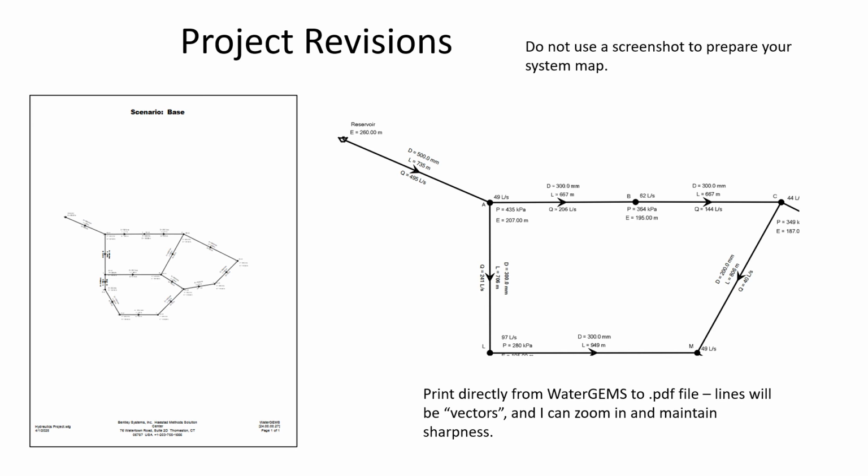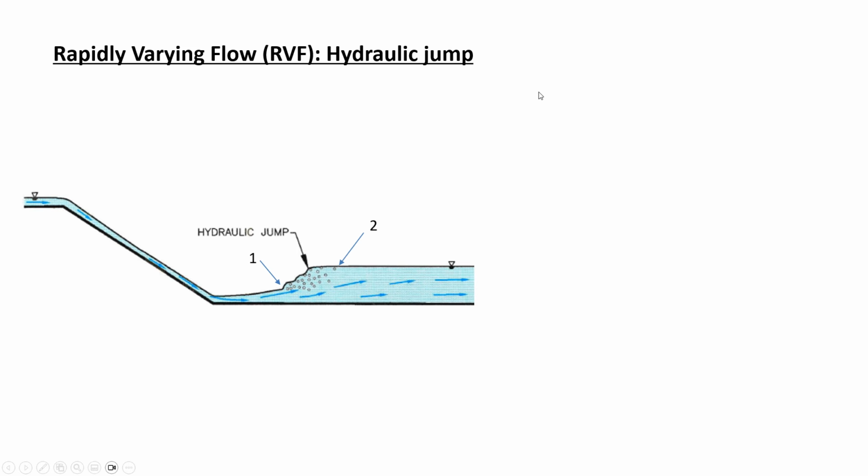It's just a matter of, once you've finalized your pipe optimization, multiplying the number of meters of each pipe diameter by their applicable cost, and then also finding the cost of the reservoir using linear interpolation between the sizes that I gave. So you should be in good shape for submitting that final report.